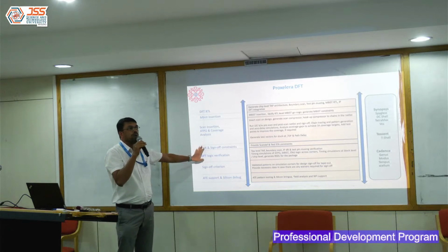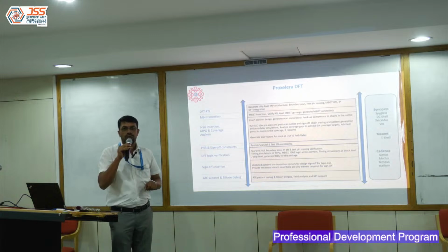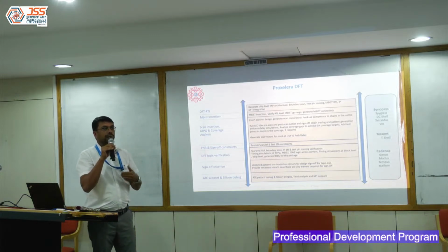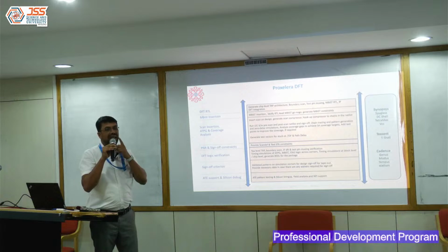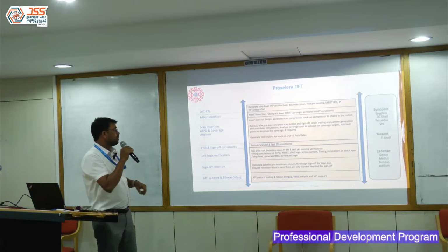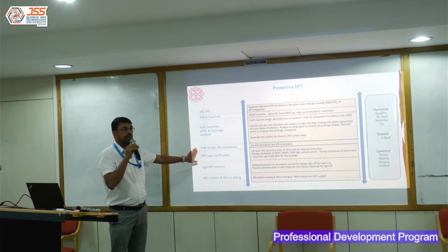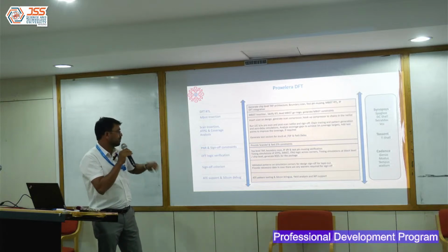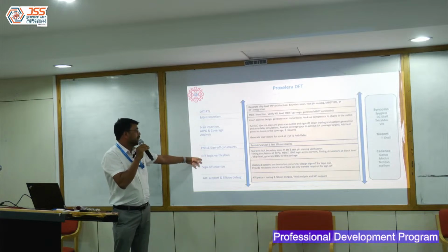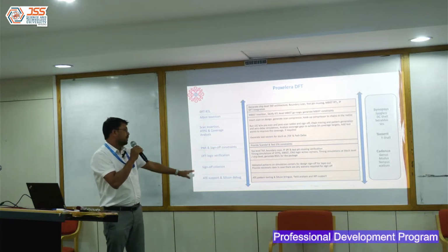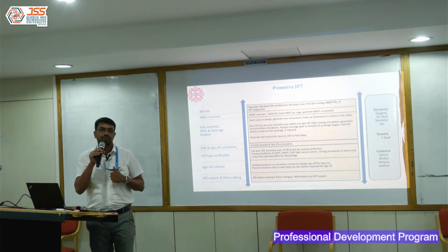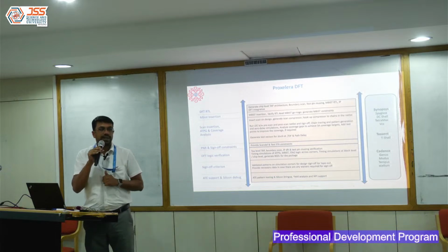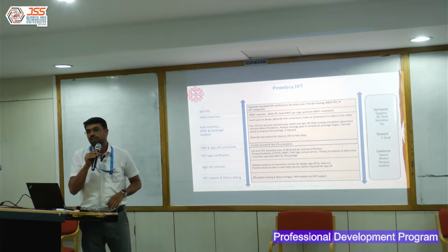And then I think you might have been having a session on physical design. So the PD team will give us certain constraints called SDF, and there the delays would be annotated. So we do a round of simulation to make sure that all the setup and hold violations are fixed. Our simulations have to pass. That is done as a part of the PNR sign-off constraints and DFT logic verification. And as a sign-off, if I want to give a thumbs up from the DFT side saying that the design is fit for tape out, all my timing simulations have to pass.